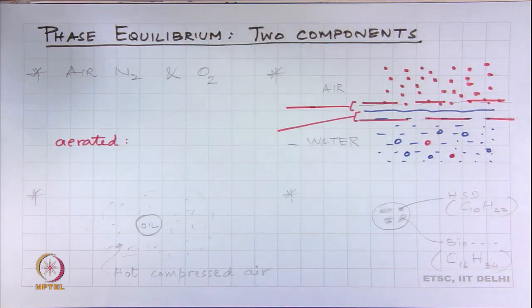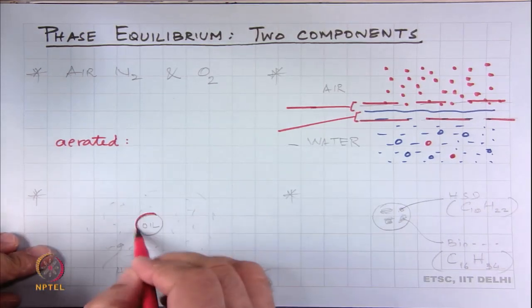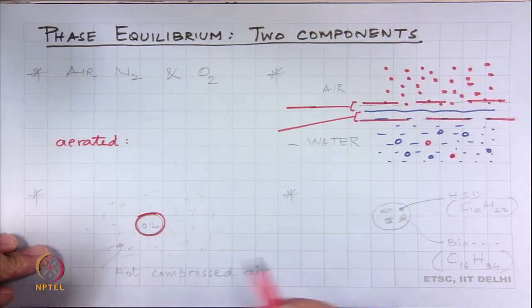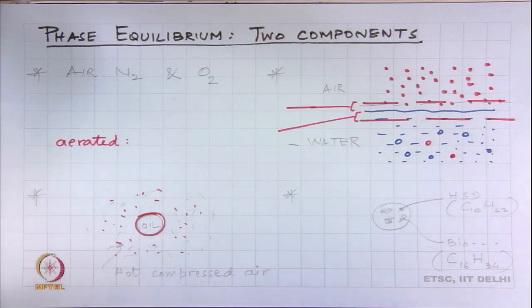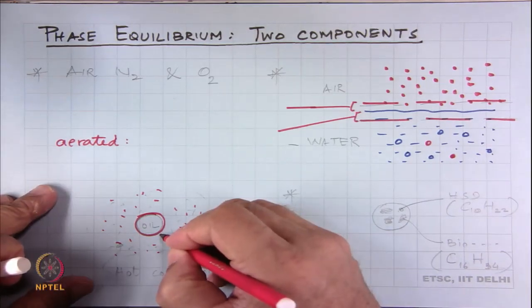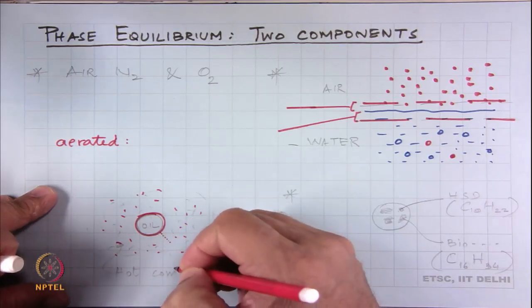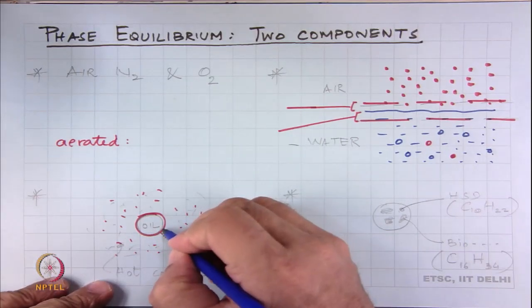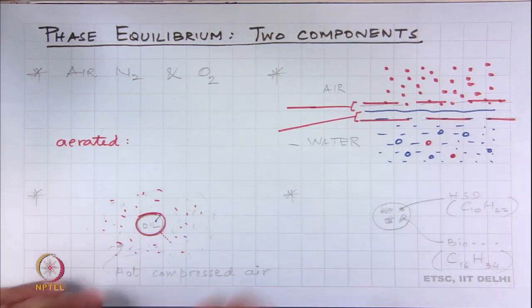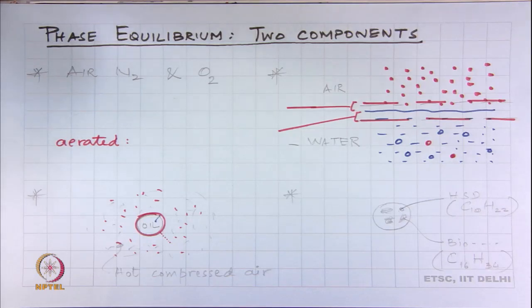Another application is an oil drop, a fuel, sent into an atmosphere, which happens at the end of the compression stroke in a CI engine, where you have very high pressures and high temperatures. One thing we were looking at is that these molecules will go out, mix with air and start burning. But now we have to worry about something: if the pressures are sufficiently high and the properties of the oil are certain, then some of this air will start going into the oil and alter the properties of the drop surface, and without that we will not be able to accurately predict how this particular fuel will burn.